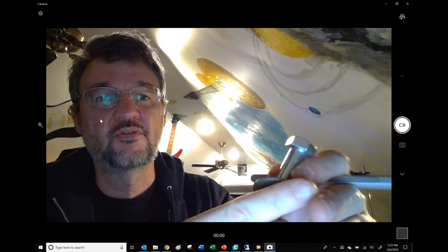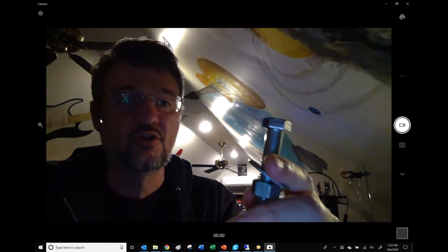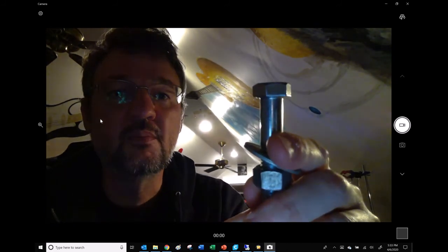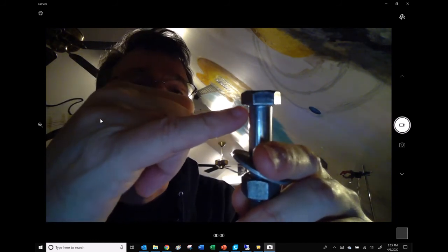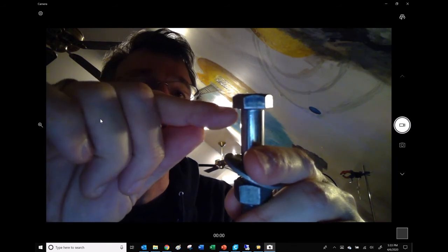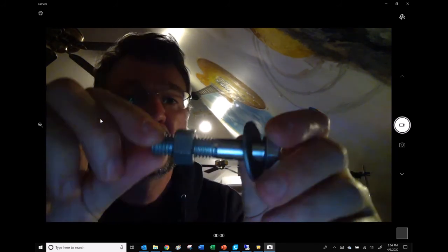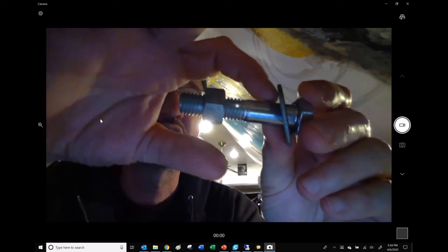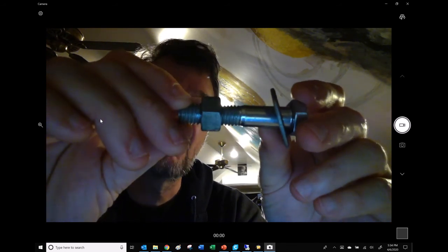I did want to look at some of the other features of the bolt while I have it right here. So you've probably seen many bolts before, but maybe you haven't looked that closely. You could try to see some of the features where there's actually a little piece right up above where things are supposed to rest, right? So it's actually supposed to be landing on right here. And there's also kind of a fillet already made into it. And then as you go down, you can see on the shank right here, it starts to get smaller right there.